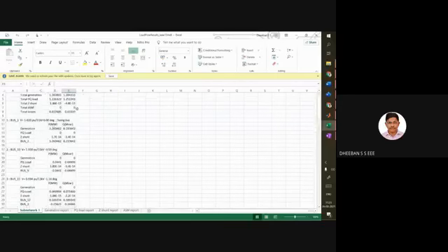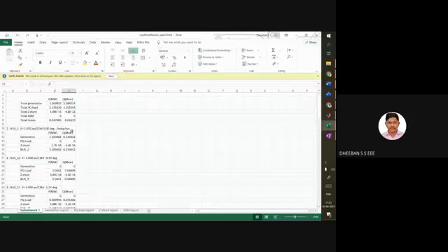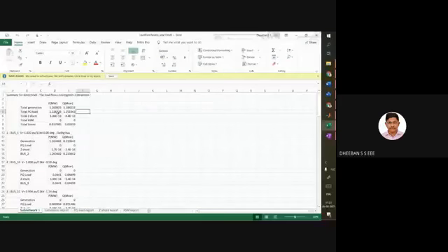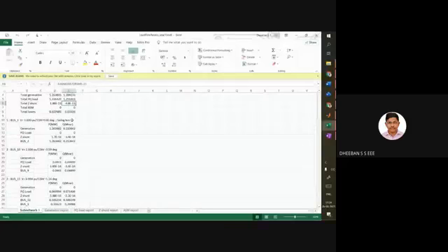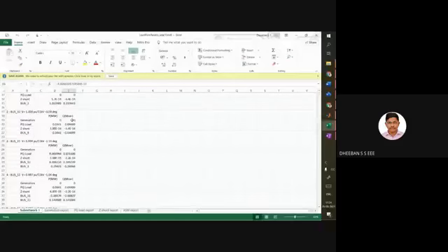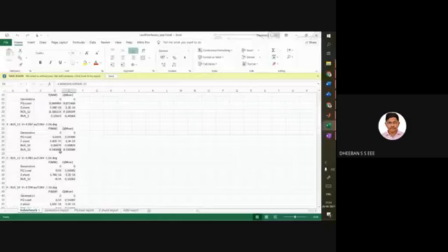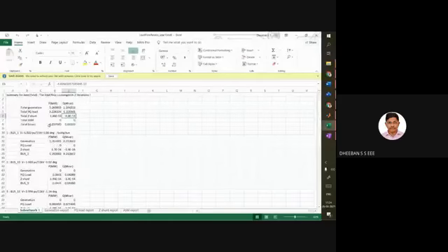The thing is that what we presented is giving a very optimal solution. Okay, for the 15 bus also I think we went through Gauss Seidel only, but the thing is it is converged. Okay, but in some cases, this iteration count will be increasing if it is not converged.